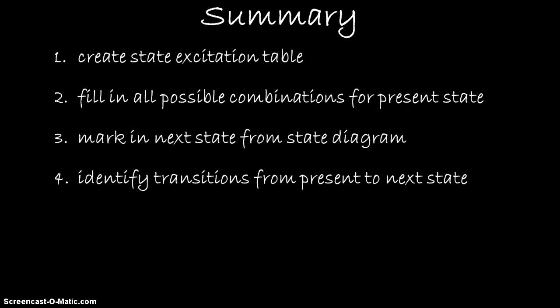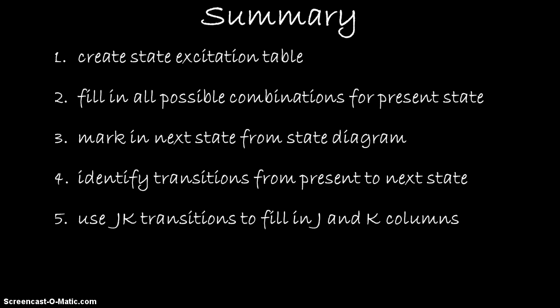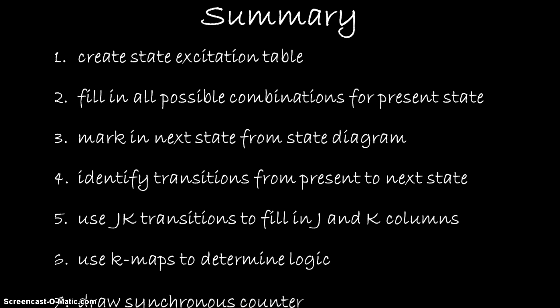Identify the transition for each state change for each flip-flop. Fill in the transition columns using the JK transition table. Use K-maps to determine the logic for each J and K. And finally, draw your synchronous counter.